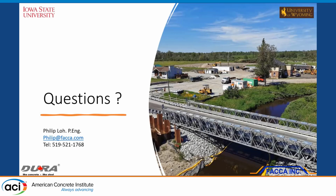That's a good question. Typically for the work that we have done, we compare the cost of steel piles to UHPC piles. With UHPC piles, we can cut down the length by about 10 to 12 feet, if the total length is about 50 to 60 feet. That's what we've done conservatively. Plus we do gain end bearing that steel pile doesn't provide.